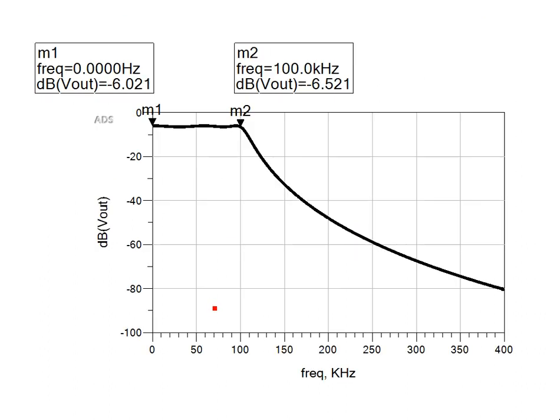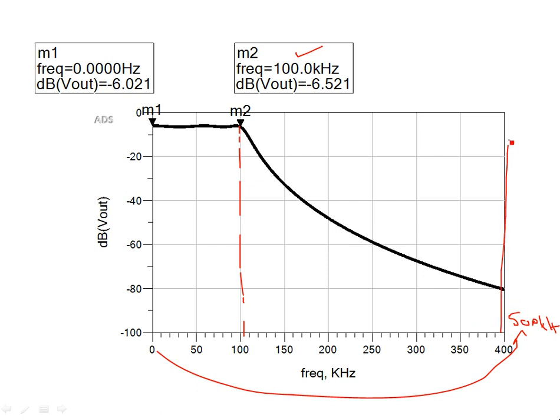Now, if you recall, the low pass filter that we constructed last time had a frequency of about 100 kilohertz. This frequency is the passband edge, and this is the bandwidth of the low pass filter. Now, what we are going to do is transform this DC to another high frequency. We are just going to shift this DC to the center frequency of the bandpass filter, and on either edge, we are going to have a response like this, with the maximum transmission at the center. On either edge, we're going to have the bandwidth.